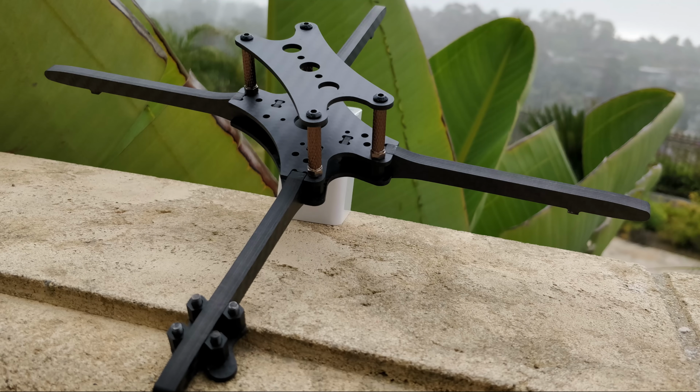That's why these frames with vertical plates, vertical arms, need to have some sort of carbon cross bracing between arms. One of the first vertical arm frames that people recognized to be something special is the Carrara Talon frame. I've always believed that the reason people think it sounds cleaner or flies cleaner is the cross bracing of the arms, which makes the frame much more rigid overall and reduces the need for filtering and everything else. So everything is running cleaner because of that. It's not necessarily because it's vertical arms.